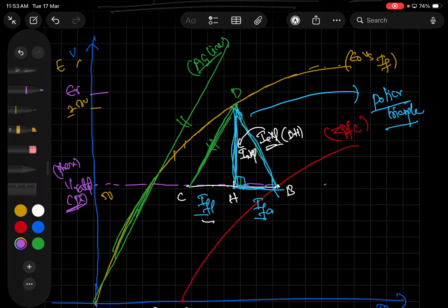What I need to do here, I have to extrapolate. I'm using a term called extrapolate. Extrapolate is nothing but draw the dotted lines onto the OCC characteristics. Draw the dotted lines from this point onto the OCC characteristics here. You will get an intersection point here.